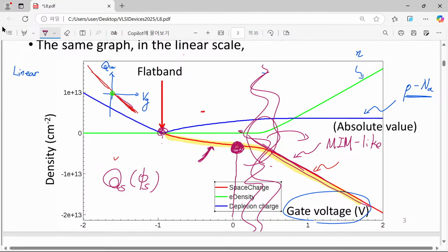Maybe you can remember two different terms. One related with depletion was the linear term, and its leading coefficient was just 1. Maybe you remember that one. And another one related with inversion was exponential, dependent on surface potential, and unfortunately it has quite a small leading coefficient. This number happens to be, for example, 10 to the minus 14, 16, something like that.